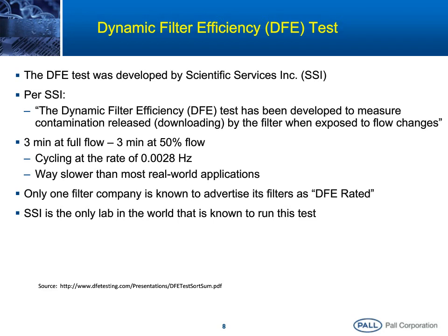The test uses flow cycling between full and 50% of the full flow for 3 minutes each. This translates to a cycling rate which is way slower than most real-world hydraulic applications. To my knowledge, there is only one filter company that uses this test method to market their filters, calling them DFE rated filters.